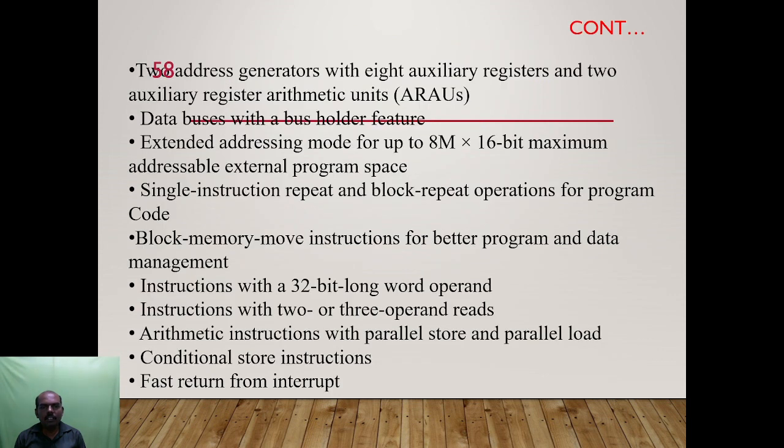2 address generators with 8 auxiliary registers and 2 auxiliary register arithmetic units; data buses with bus holder feature; extended addressing mode for up to 8M 16-bit maximum addressable external program space; single instruction repeat and block repeat operation for program code; block memory move instruction for better program and data management; instruction with a 32-bit long word operand; instructions with 2 or 3 operand reads; arithmetic instruction with parallel store and parallel load; conditional store instructions; fast return from interrupt.